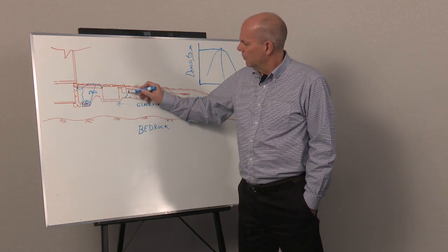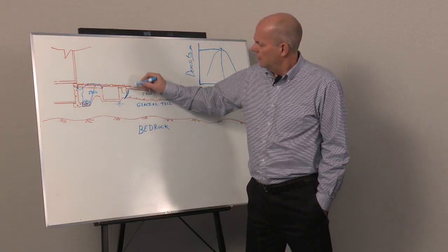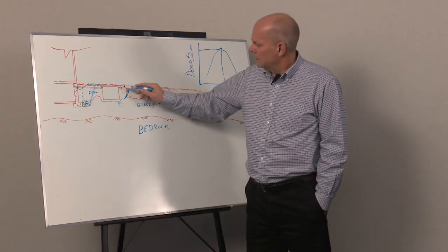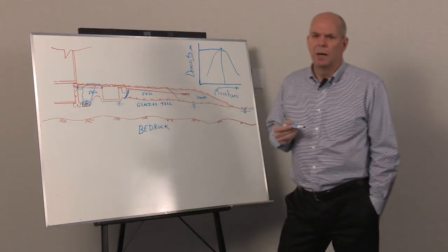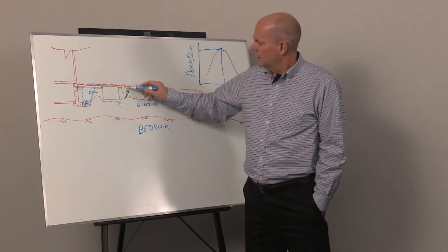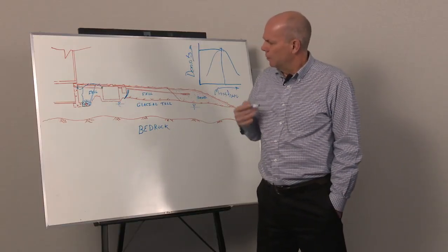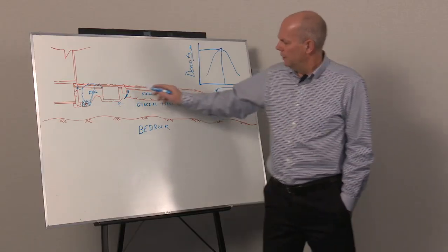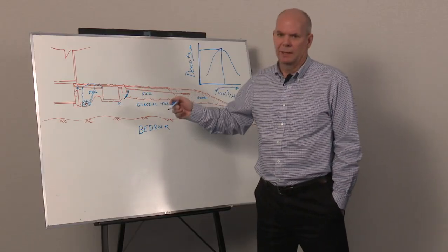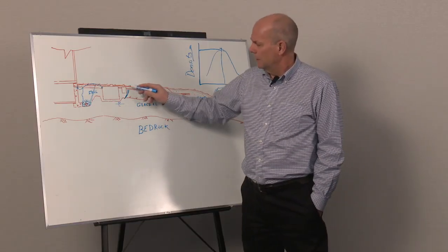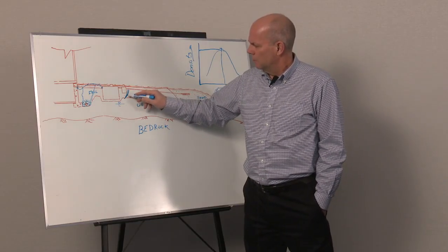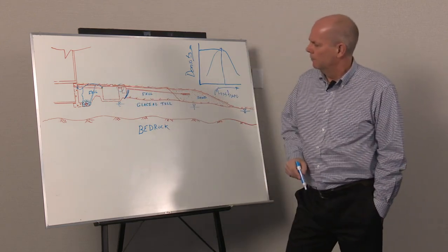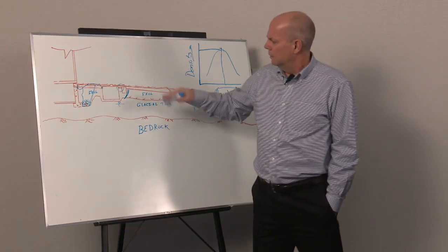This excavation for the tank and the adjacent pump chamber may be such that the pump chamber or the siphon box is sitting up in the fill, and you have the same conditions there. You have to place that fill, replace it properly, compact it, or else you're going to get settlement and cause differential movement, which causes issues with the effluent pipe in between moving around.